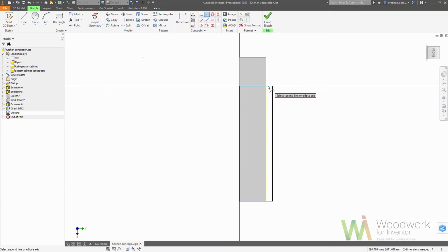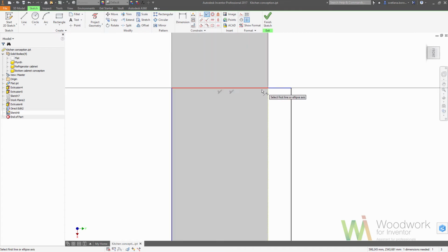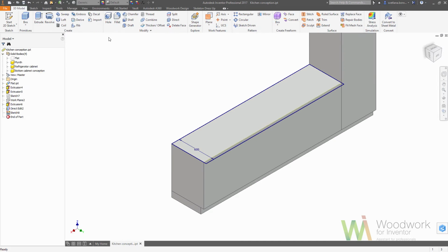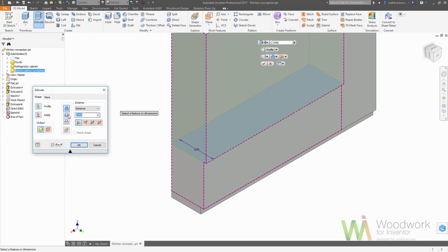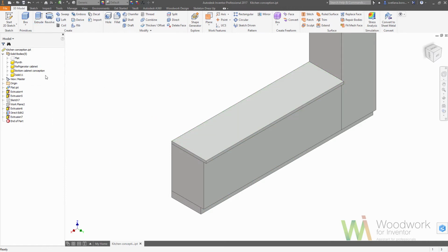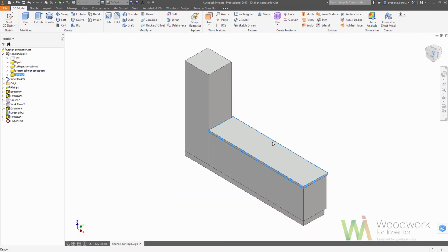Because the desktop is of the fixed depth, because it's made from the profile, we need to define the depth of the desktop. Okay, and now again let's make a new solid body with the thickness of the desktop. There is a simple rule. New solid body means the new part in your final assembly. But now we are still working on the concept.